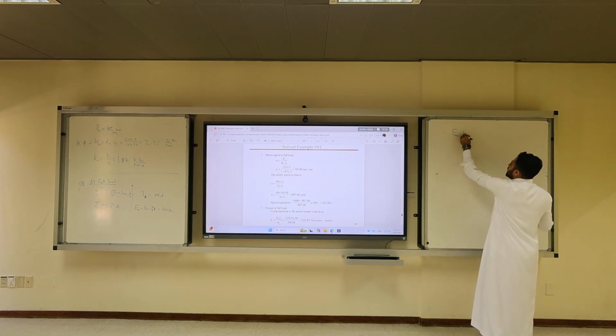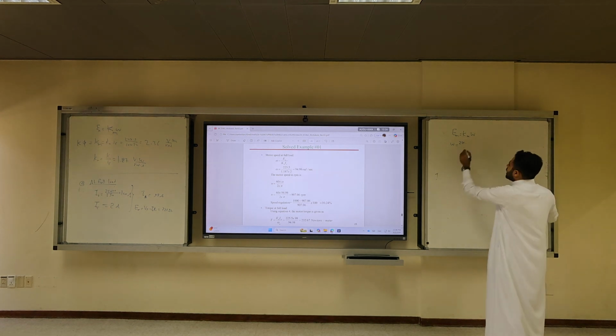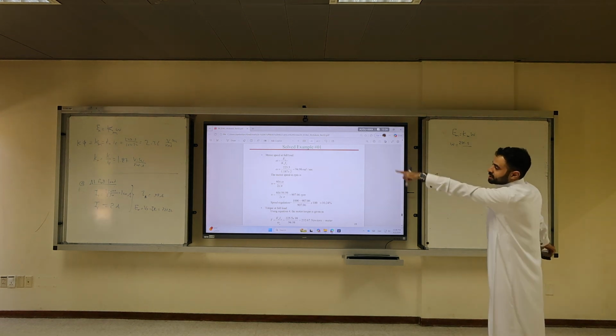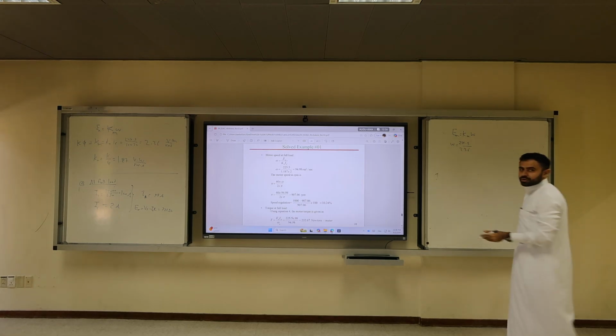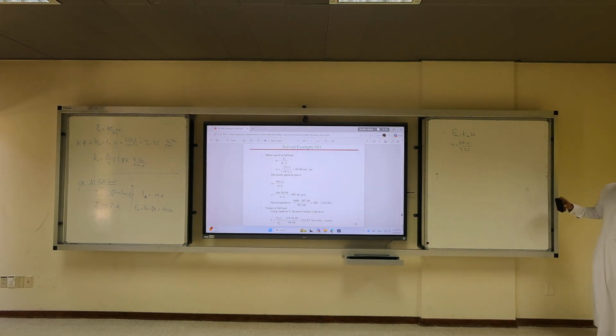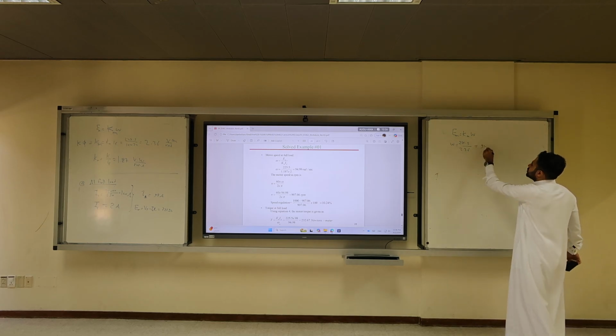We use the formula EA equals Km times omega. We have EA, we have Km. What is omega? 225.5 divided by my constant, not the slide constant, 2.36. The project constant, the motor constant. If you do the math, you should get the same answer, 94.98 radians per second.